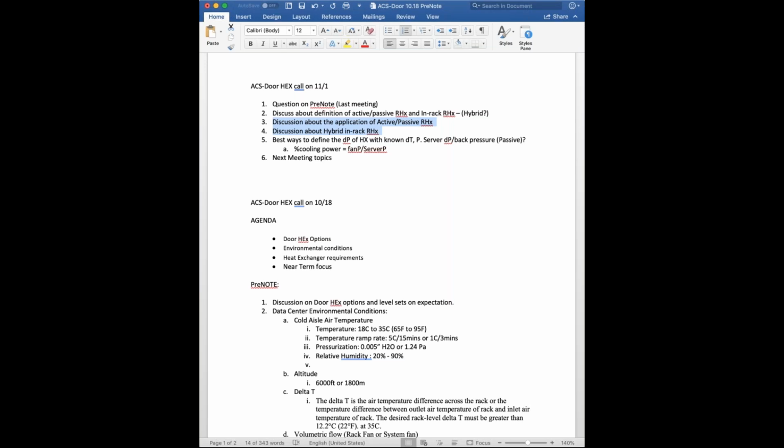I can agree, and of course, if we go to chip cooling, you need a connection per rack to the facility side, to the chilled water side. So the connection is made, so the water is in the rack, and you can say, let's also cool the resistance heat that's left from other components, but by a coil in the back door. And if it's only for the last 20 or 30%, it can be a cheaper, smaller, easier coil than, for instance, for 50 kilowatts, of course. So it makes sense, but it's something else than it is applied to today.